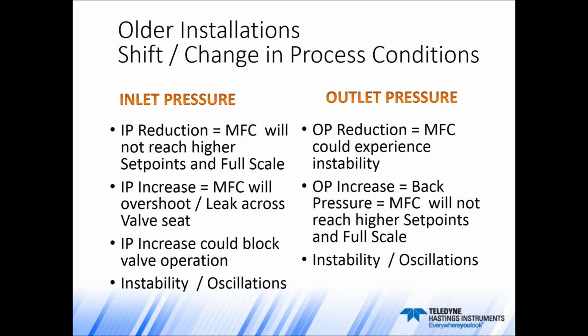An inlet pressure increase could actually block the valve operation. There's a certain dynamic on the proportional valve that has to do with how much pressure is needed in order to lift, to allow the magnetic field to lift the valve seat from the orifice. If that pressure increases dramatically, the magnetic field might not be able to lift the valve seat off the orifice. So as a result, you're not going to have control.